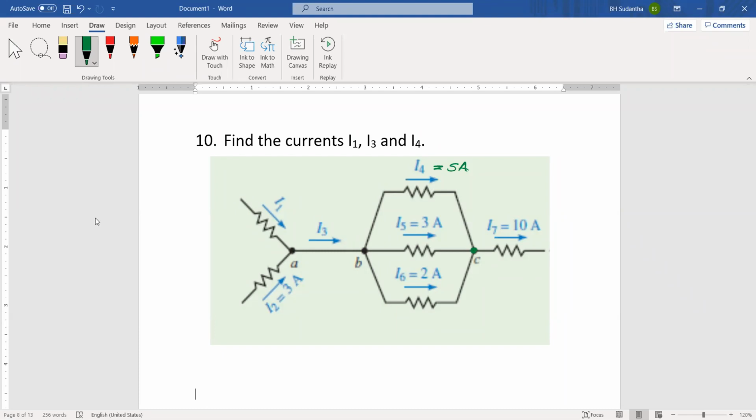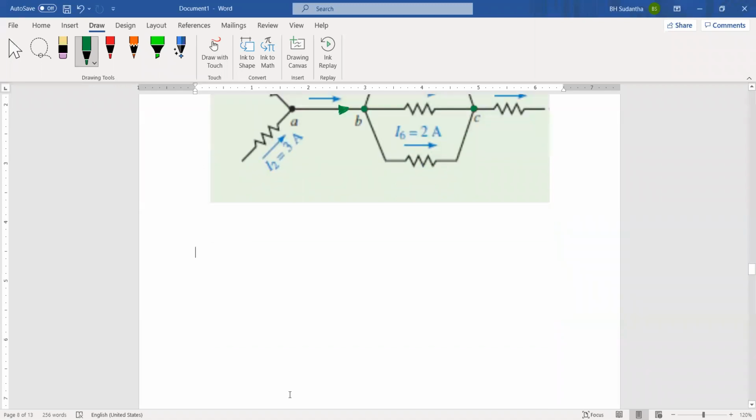And what about this current? This is the incoming current, because this is definitely 10 ampere. Okay. When you consider this incoming current of this node and these outgoing three currents, they should be identical. And if this current is 10 ampere, and 3 ampere current is coming from this side, then definitely this should be 7 amperes. Okay, shall we try this one?